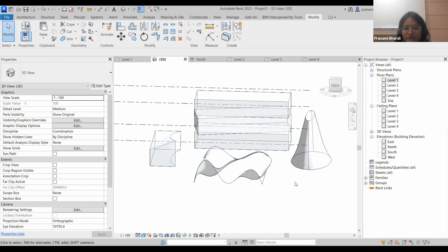So if I talk about the facade, in a facade, what can you have? Maybe you have very parametric panels, right? Curtain panels, maybe hexagonal, maybe octagonal. Those panels you want to place in the front facade accordingly, right? So Revit even allows you to do that also. In the massing environment, you will just create how the mass will look, maybe a parametric roof or a waffle structure form accordingly, or the building form.